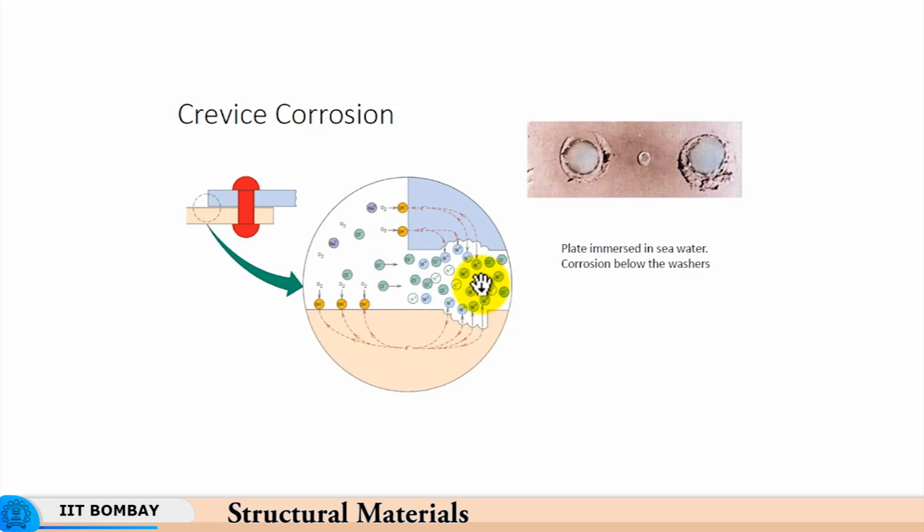Had oxygen not been dissolved there, then the H plus ions would also have been present and would have competed with this reaction, or would have reduced the attack. So, by presence of dissolved oxygen, the rate of corrosion gets aggravated or accelerated.